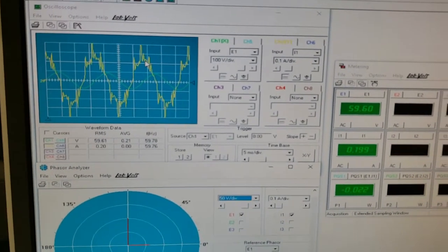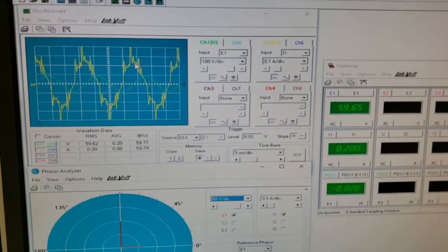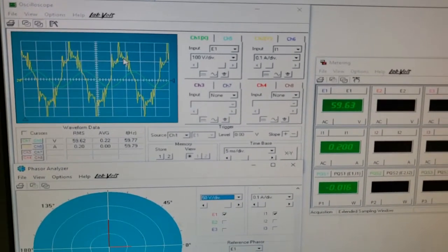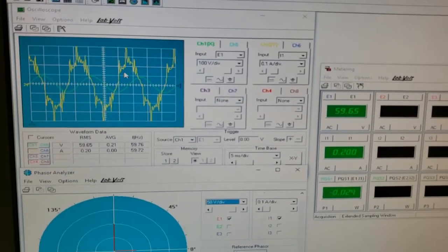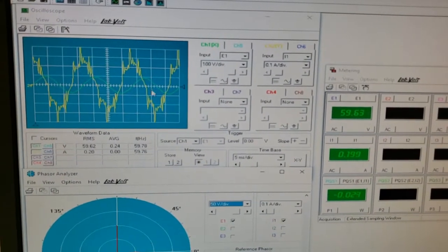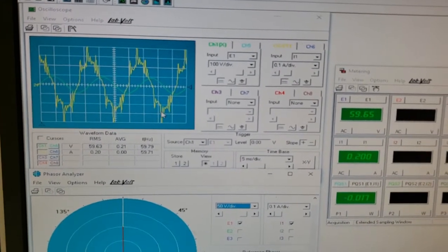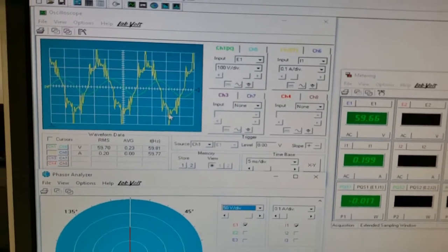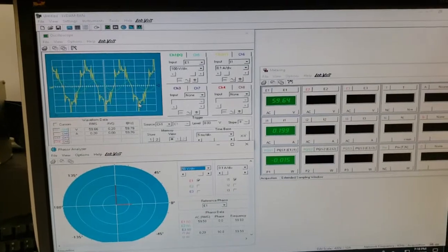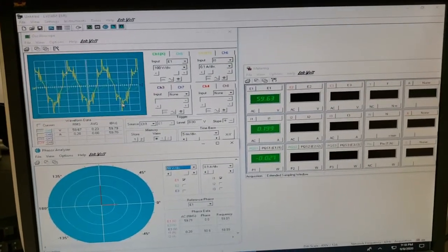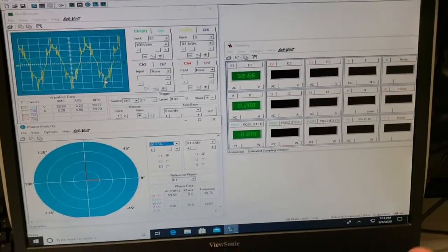Depending on the properties of that dielectric, that oil, if it was very nonlinear in the operating range we're using, so if at 60 volts it's very nonlinear, then you will see a lot of added harmonics. By nonlinearity, I'm not sure if you've taken it yet, but if you took transformers and observed saturation, that hysteresis curve for a magnetic core, well, dielectrics have the same thing, except instead of magnetic fields, we're looking at electric fields.